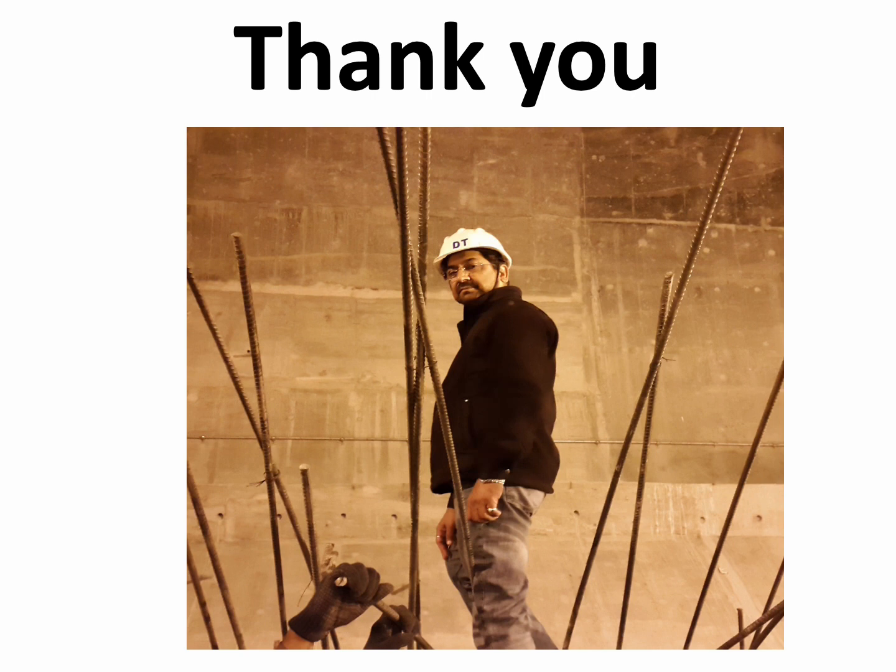I hope I am able to explain what in my thinking was the mechanism behind the failure of the rock mass in the Downstream Surge Gallery, which extended to make a cavity 91 meters high, as explained in my presentation, and also corroborated by the Norwegian Geotechnical Institute and by the National Institute of Rock Mechanics.